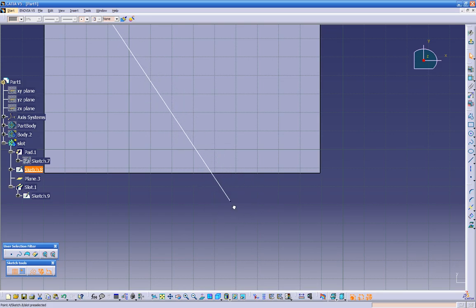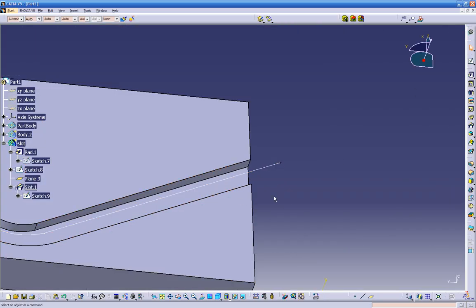But if you don't want to move it this way, let's do Control Z. And you want to go same direction. There's a couple of ways of doing this. You can create a line, and then make sure this is in the construction. And we can go to the trim option. So you can grab this line, and we can trim it with this line. That's one way. Control Z to put it back, or we just click on this right here and just same thing. Okay, so now if we get out of the sketch mode, our model is automatically updated.